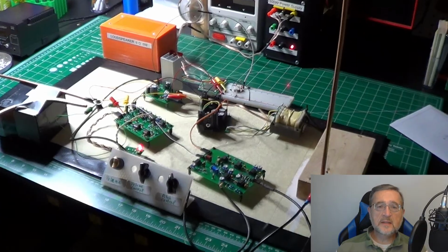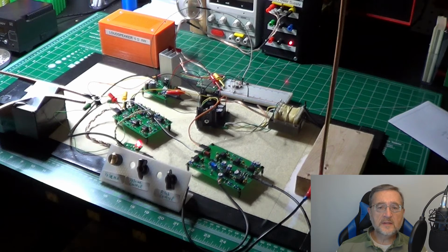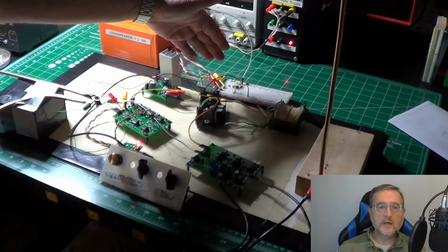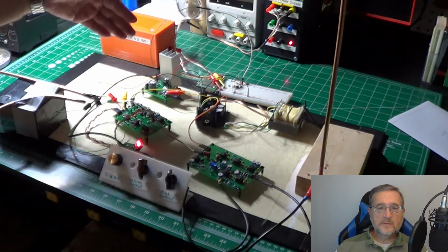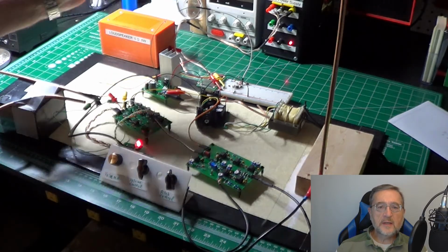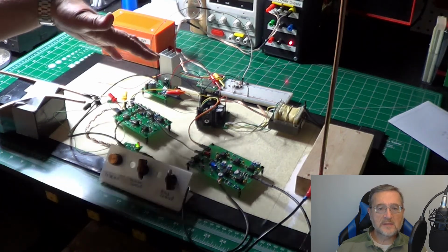Let's now run a test along with all the other Theremin units. I have connected the audio low-pass filter in between the volume control unit and the audio amplifier. This way the Theremin audio signal will be filtered before being amplified, so that it will take out the majority of the harmonics from the sound and leave only the fundamental sine wave.